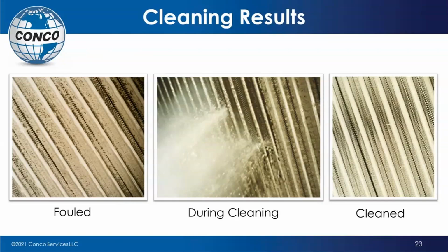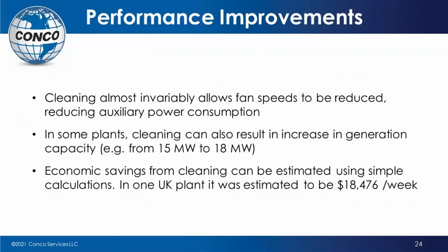And in the end, of course, you want a clean unit so that you have free airflow through that system to give you the highest efficiency possible. What this does is give you an immediate performance improvement. So when you're done with the cleaning, and you start that fan back up, you should see an improvement right away.